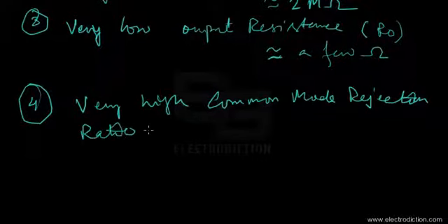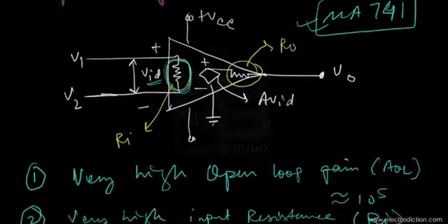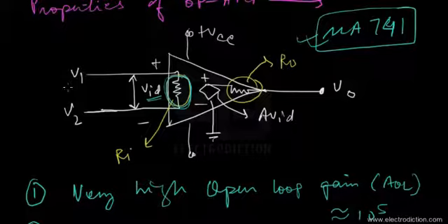Okay, so common mode rejection ratio, that's quite a mouthful. We can call it CMRR in short. The common mode rejection ratio actually means how good the op amp is at neglecting the common mode signals and amplifying the differential mode signals. I know that's quite a few terms, so I'd like to simplify this topic.